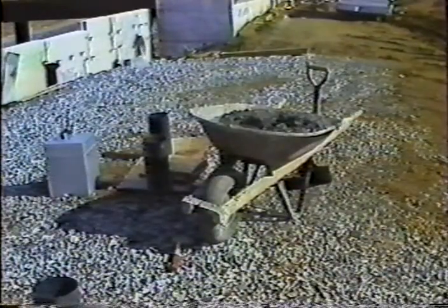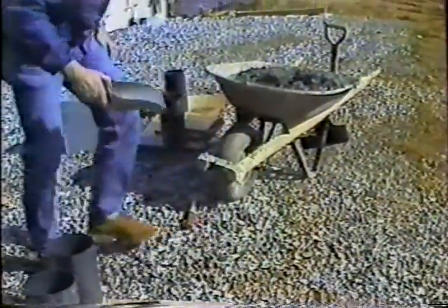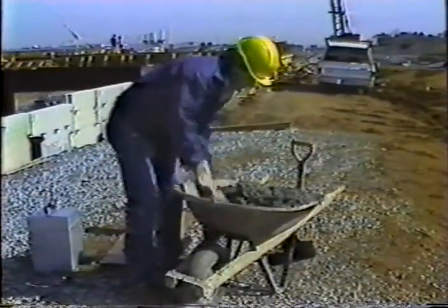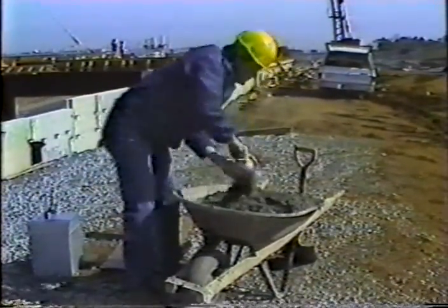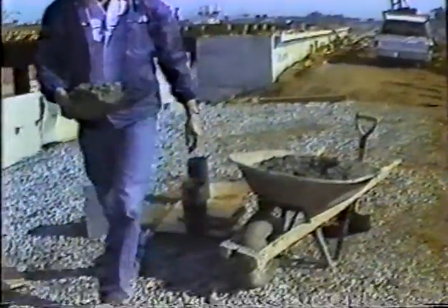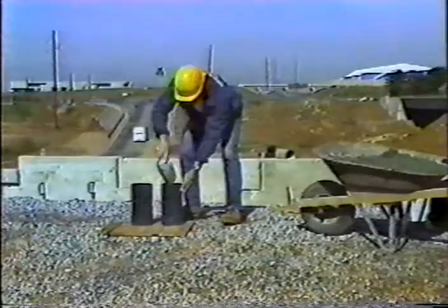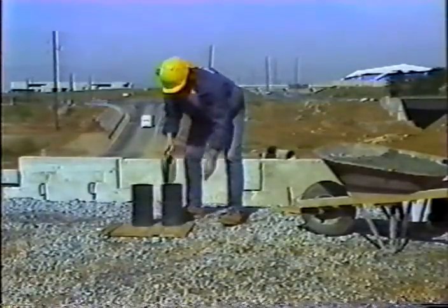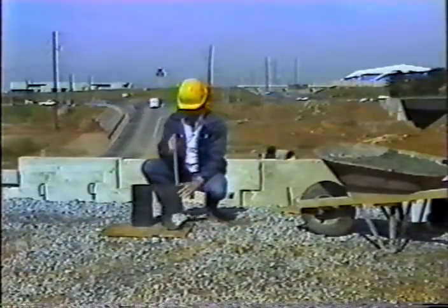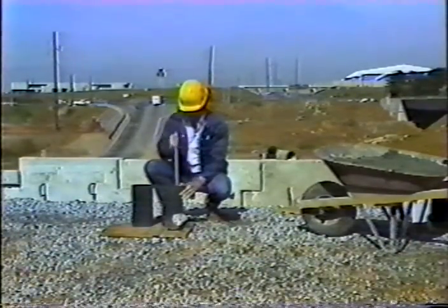You'll need a random sample of concrete, as you saw in part 1 of the course. Be sure to get enough concrete to run all your tests without reusing any of it. Place the first layer into the mold, moving the scoop or trowel around the lip of the mold. If the concrete isn't distributed evenly inside the mold, use the tamping rod to move it around. Rod it 25 times, spiraling toward the center. Full depth for the first layer.